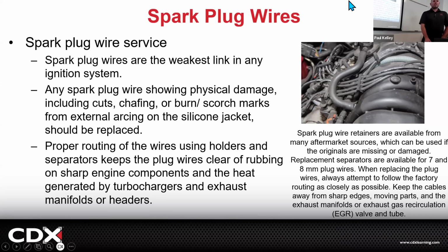All right. So if we're looking at this, you want to know how I would test it? Of all the tools and all the specialty items, I like the KISS method. So I'm going to test it with Windex. Or actually, I'll just take the Windex bottle. I'll put water in it, but Windex would work too. And I'm going to literally mist Windex or water in a spray bottle on these wires, and I'm going to do it while it's running.